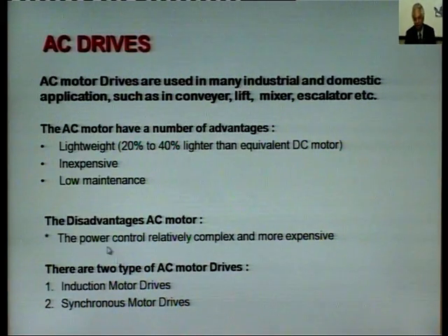The motor part is the advantageous part, but if you see the whole drive, that is the motor along with the power unit and the control unit, there are 2 units, one is the power unit, another is the control unit. The control unit is relatively complex and more expensive compared to DC drives. There are 2 types of AC motor drives, one is induction motor drives, the other is synchronous motor drives.